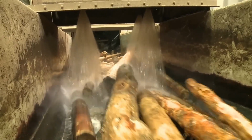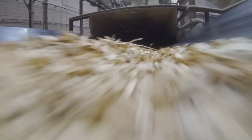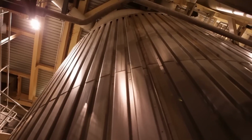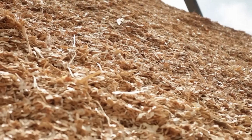Next, the wood is washed to remove stones and sand and controlled by metal detectors to prevent nails or screws from damaging downstream machinery. Rotating blades then further reduce the wood into small pieces, which are finally stored in large quantities. These fragments then undergo a chemical process in huge industrial tanks to be turned into pulp. During this cooking, which can last up to 3 hours, most of the moisture is evaporated. This process produces a usable fiber called pulp.